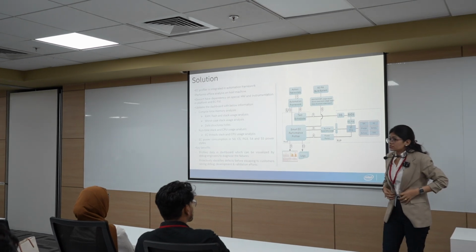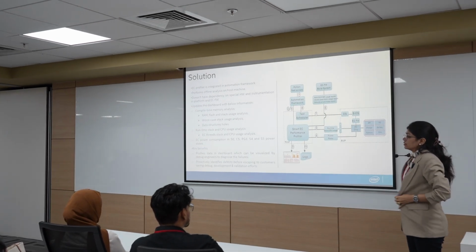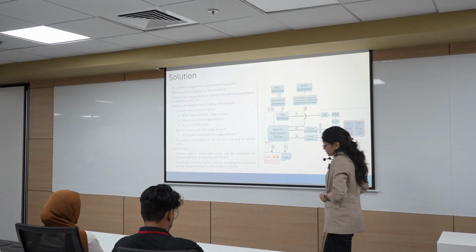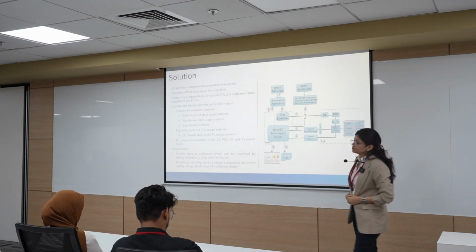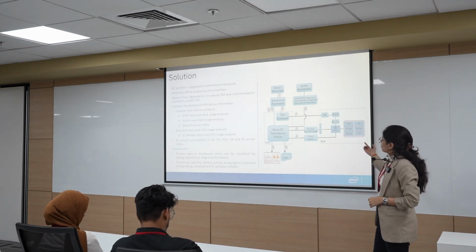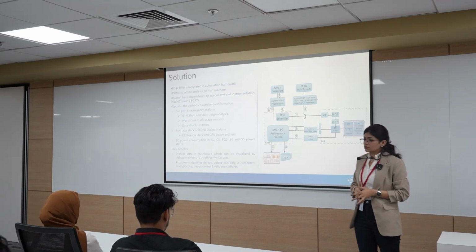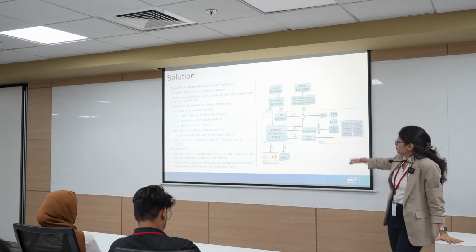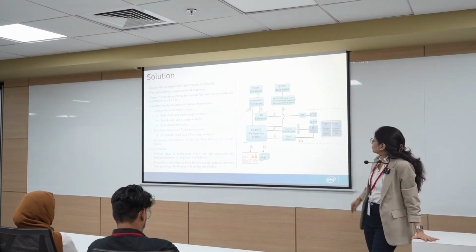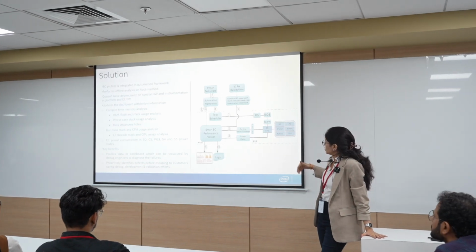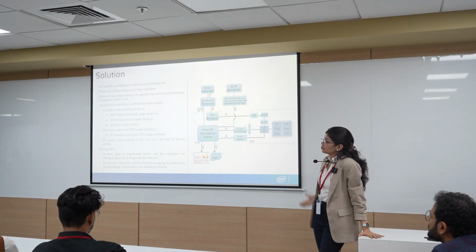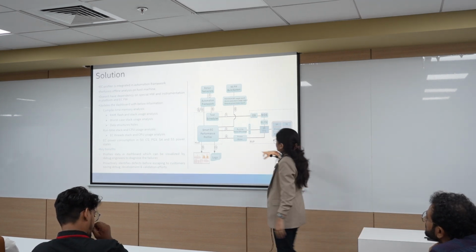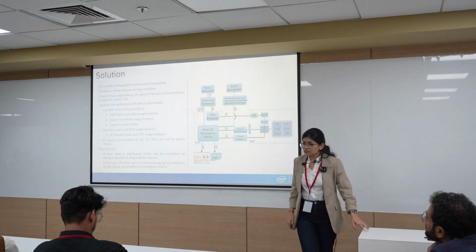When I say stack usage, Zephyr calls it puncover. Puncover is a third-party tool which you need to run after you build your EC firmware code. The other one is pahole, the data structure hole tool, which tells us how many holes occurred in your data structures when you add them into your EC firmware code. And the third tool we use to get the runtime stack and CPU usage data is the thread analyzer.